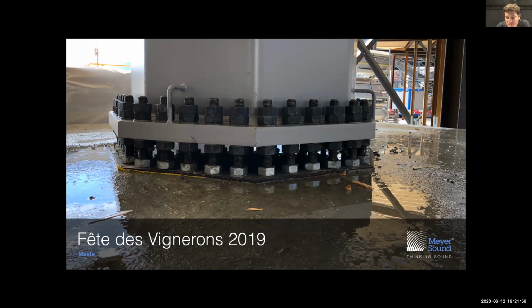Also, Jean-François did a bunch of tests in Paris where he put dynamometers in the motors, so they could verify what the dynamic load was when the array is going up. The array weighs 2 tons, but when it's moving and traveling across the chain hoist for 20 meters, we wanted to know what the loads were on the platform, so that we could get a safe margin by moving everything, and what would happen if we get a little bit of wind, which eventually happened.